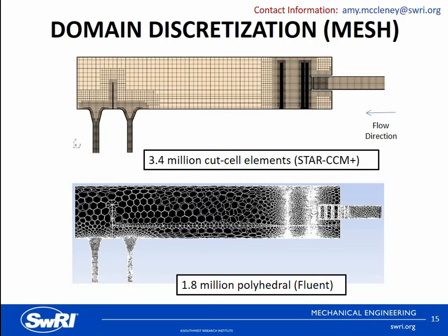Meaning the doubled grid resolution did not offer anything in terms of getting a better result, but did have a significantly higher computational cost, meaning they took a little bit longer to run. So we decided to keep the meshes that we have here as the ones we use throughout the entire parametric studies.